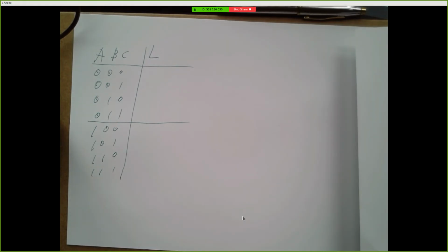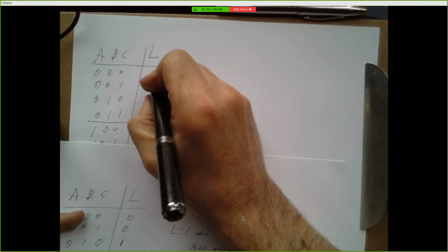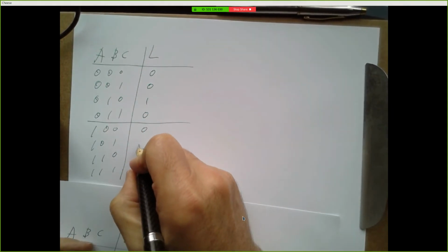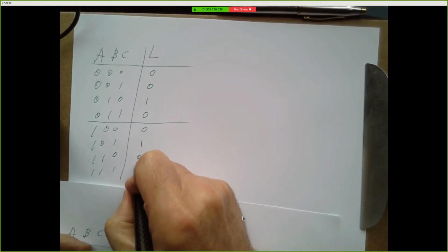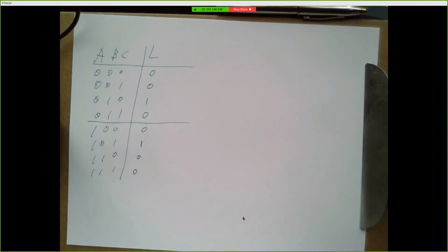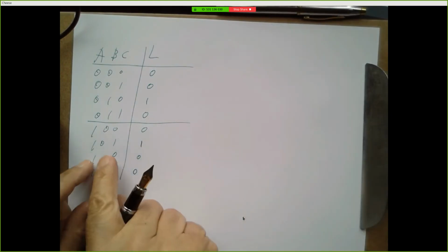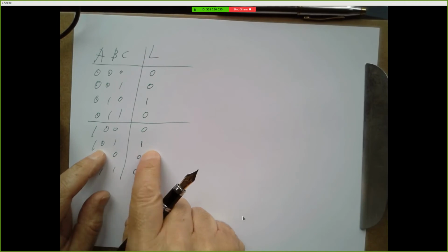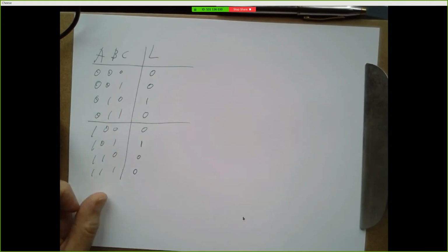But you don't want to give them your combination, because if you kick them out, they would have your combination. They could come back and eat cookies, right? So we want two combinations that unlock this circuit. So we want a truth table like this, so that if you put in the combination 1, 0, 1, that generates the unlock signal, but also if you put in 0, 1, 0, that generates the unlock signal too.